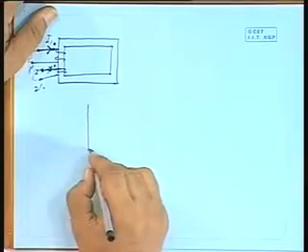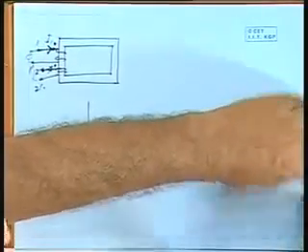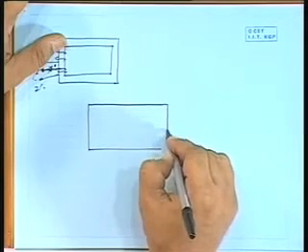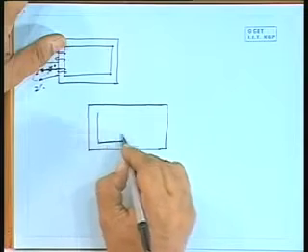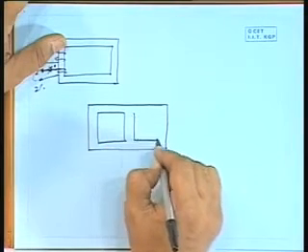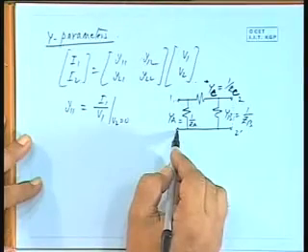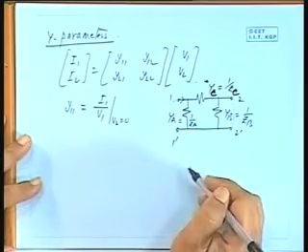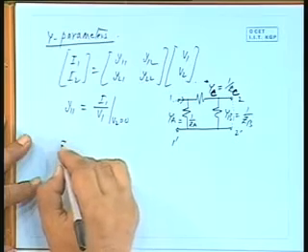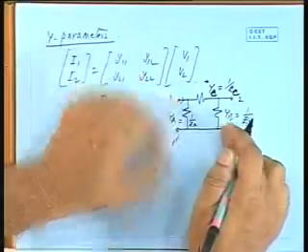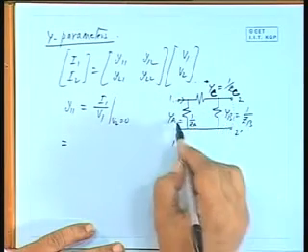Now I give you an example. You try to find out whether this particular coil arrangement and the dot conventions are correct. You are having a toroid with a central limb. Now you apply a supply voltage here and measure the current I1 after shorting this. So how much is it? It is the admittance seen from 1 dashed under this condition. So it is 2 parallel elements, YA and YC.